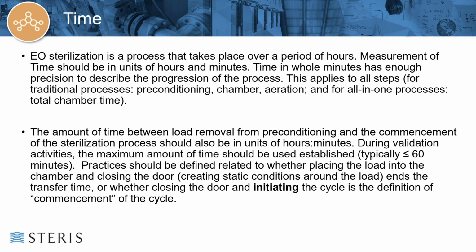So time, usually the maximum amount of time that you set for your cycle can be based on the heat history that you used when the medical device manufacturer was establishing the shelf life, doing accelerated aging, etc. If you look at the amount of heat history that's delivered to the device that established your testing and whether or not your product functioned after all of its manufacturing processes, after sterilization and after aging, you may be able to say, hey, our product is able to take 130 Fahrenheit for up to 90 days accumulated heat history